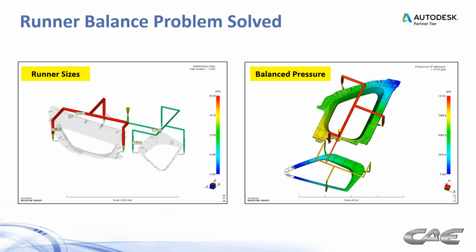And in some cases, we have to balance not only the hot manifold, but also the cold runners to get the kind of flow pattern we need, where both cavities are filling simultaneously, so that we get relatively similar pressures in those cavities, so that they have a chance to pack out more uniformly between the two. In the case of multi-cavity molds, where we have all the same parts, but we don't have a balanced runner design, some artificial balancing of cold runners would be necessary as well.